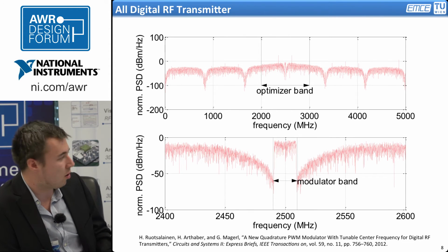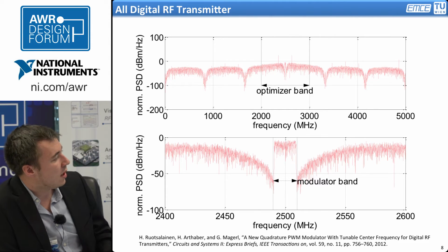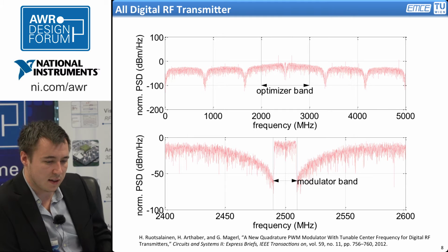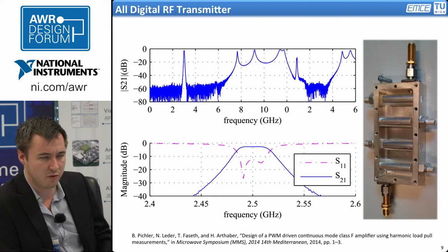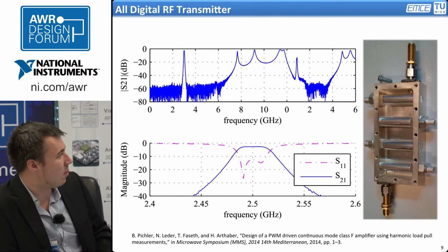And since my colleague already introduced this chart, I just want to briefly sum up. As you can see here, the output spectrum of the DAC is very densely populated. There are some energy-rich components all over the place, and we are just really interested in this LTE signal here in the very center. So we need a very selective reconstruction filter that is, on the other hand, also highly reflective in its stop band. So we went with a custom-built fourth-order interdigital filter, where you can see here the transmission curve.